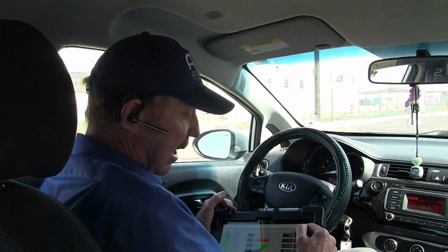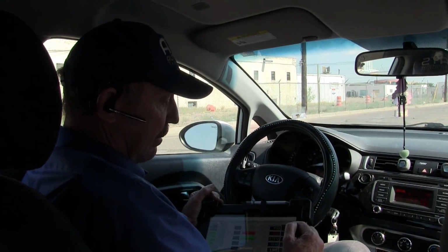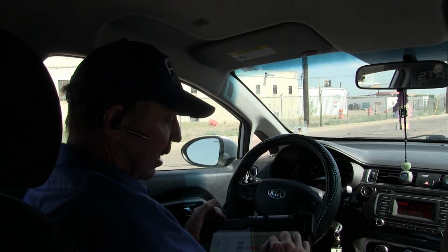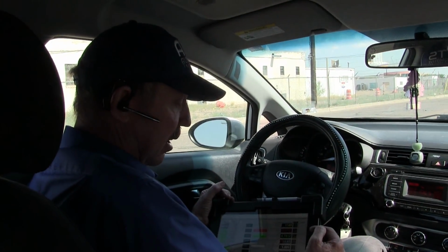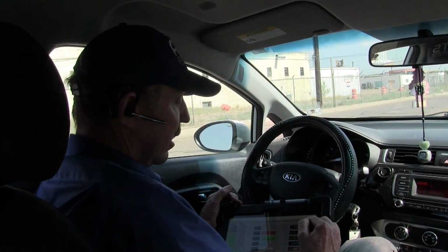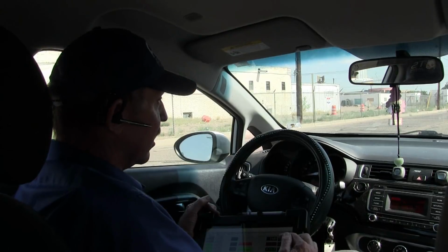I'm trying to figure out, because that had a low output, like something might be wrong with the wiring or the sensor. So I'm just trying to see if this might be a real problem with the high pressure pump, or it's just a sensor failure. And I don't know if you can do that without a scope, but we're going to try to just see what we can do with the scan tool.